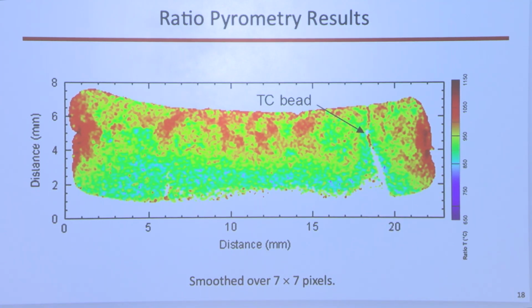We do believe that since it's calibrated with the black body across the same temperature range, we have accounted for the emissivity and the transmittance of the ash. And we get almost 500,000 pixels of temperatures here. The temperature range is shown there on the scale, 650 to 1150 kelvins.